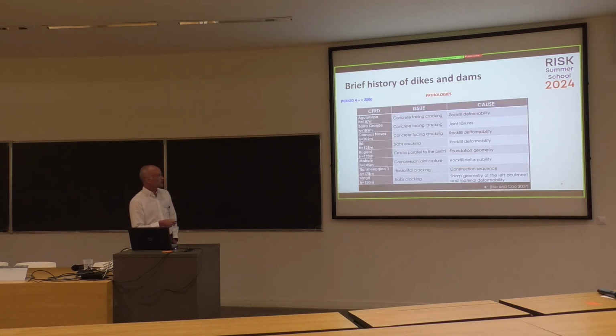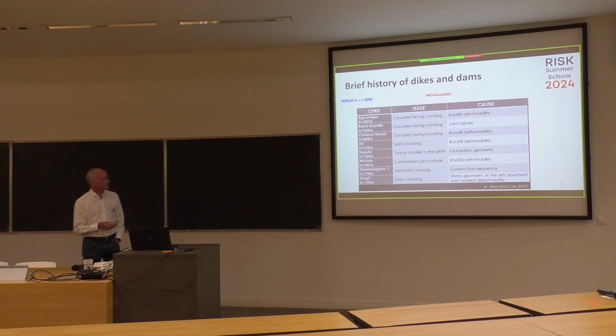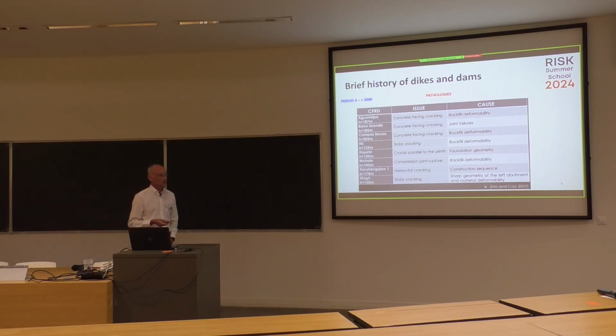In the next slide, I list some accidents on this type of CFRD dams between 2000 and 2010. And what is remarkable is that the cause, for most of them, is related to the rockfill deformability. Yes, this is the case for the Campos Novos, for Mohale here, and some other dams.